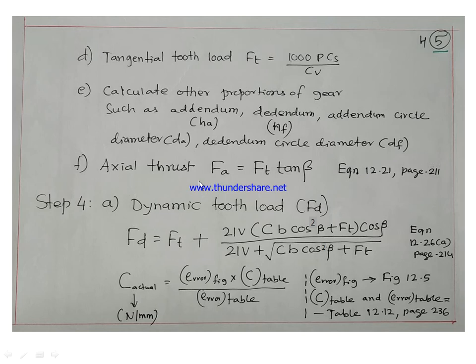And one more parameter that comes in the design of helical gears is the axial thrust, which is given by Ft, tangential load, into tan beta. Then we need to check the gears for the dynamic and the wear loads. First, we'll see the dynamic tooth load.